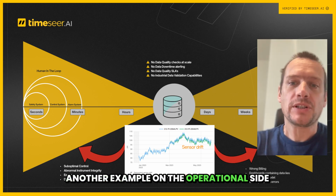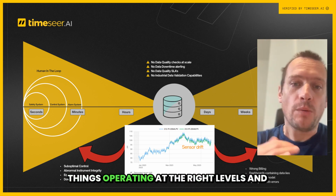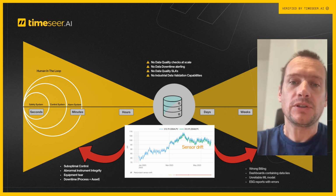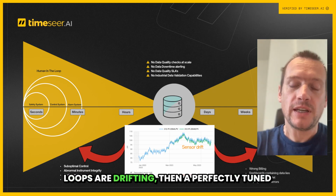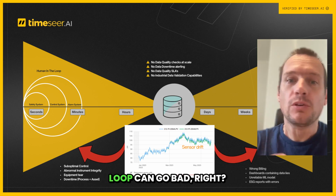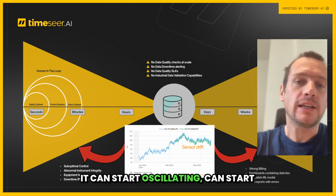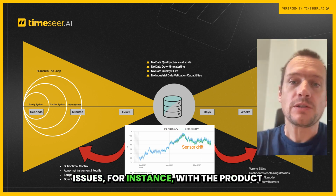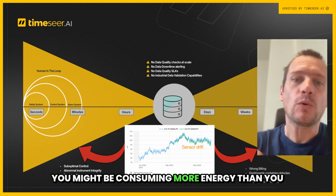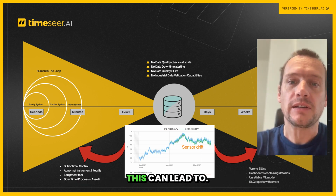Another example on the operational side would be control loops. Many factories have control loops to keep things operating at the right levels and regimes. If the sensors that are used in those loops are drifting, then a perfectly tuned loop can go bad, right? It can start oscillating, it can start saturating, and you might have quality issues, for instance, with the product you're producing. You might be consuming more energy than you want. So there's all kinds of problems that this can lead to.